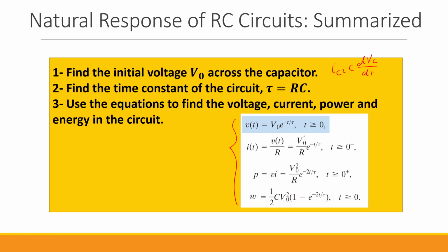So the voltage is an exponentially decreasing function because we have some energy that is being stored in the capacitor, but since the resistor, or the bunch of resistors, that you connect to the capacitor with initial energy or initial voltage always consume energy, over time the voltage of the capacitor drops because those resistors consume the energy that was stored in the capacitor.